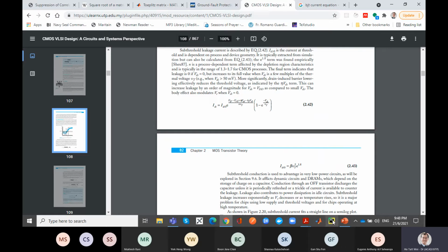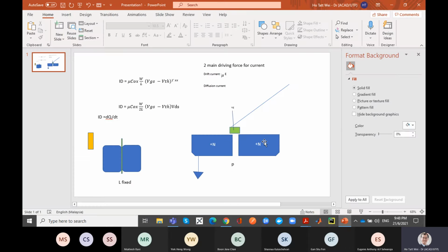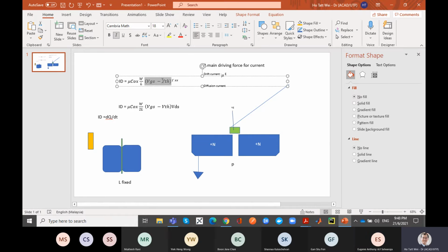The big picture here we're trying to get at is this. They throw all the equations and all the explanation at you to give you an understanding of the basic physics behind all of this. But at the end of the day, the simple point is: these are all the levers to change the current, and VTH. The device is somewhat sensitive to the threshold voltage.